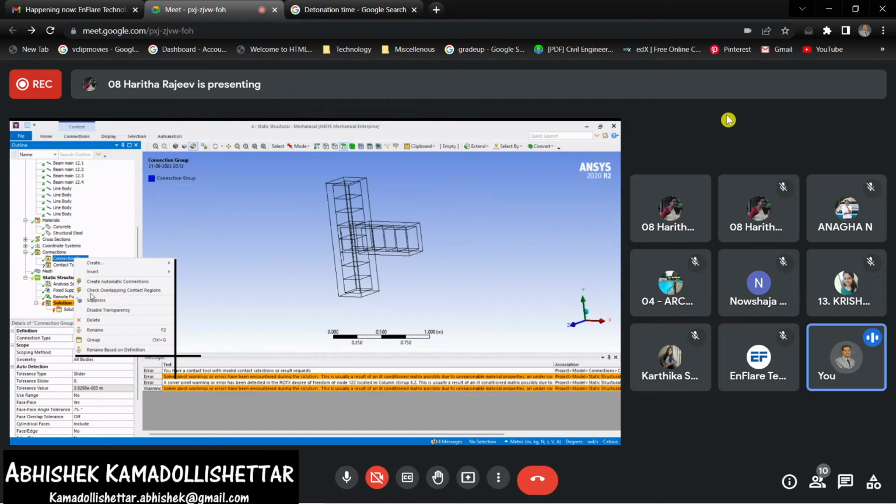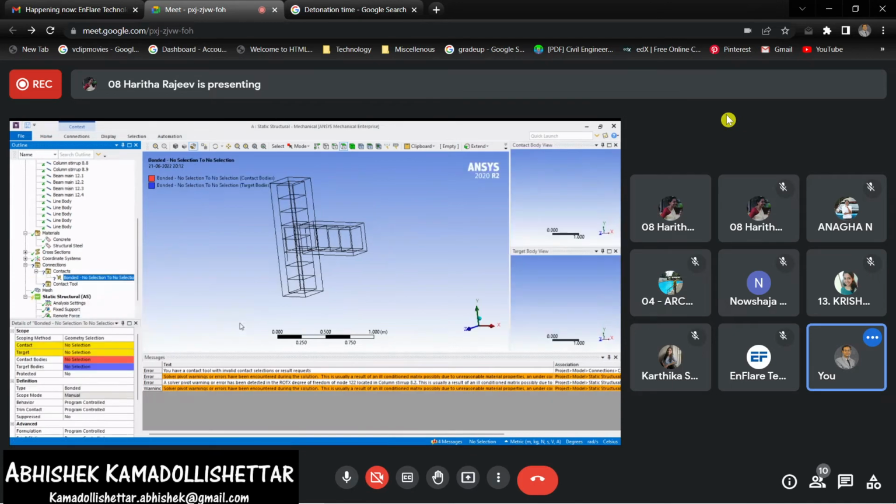Create. Just select the insert below. Go to insert. Now it is there here, this one I was searching: manual contact region. Select manual contact region. Now there is no contact zone defined. You can see here there are no contacts. Now make the reinforcement: select all the reinforcements in the diagram and make them as contact, and the target is your concrete.